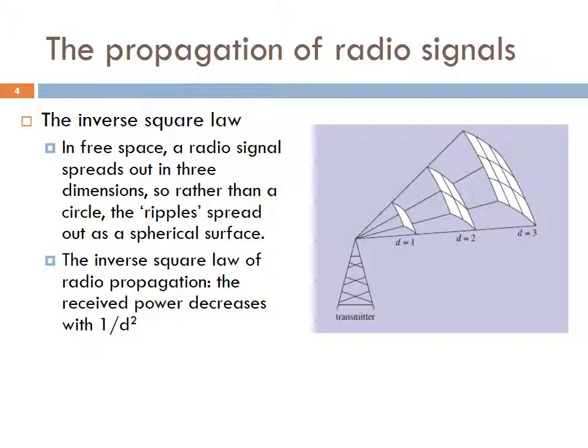This is called the inverse square law of radio propagation. So, in free space with an isotropic transmitting antenna, power received by a fixed size of antenna varies according to the inverse square law. In free space, I repeat. However, communication on the surface of the Earth is not always as simple as this, although the inverse square law must operate. In addition, there is the ground to consider: the atmosphere, the weather, the mountains, the valleys, people, vehicles, any other objects on the path between the transmitter and receiver. This can all alter the propagation of radio waves, sometimes dramatically, and the effects are described in the following parts.